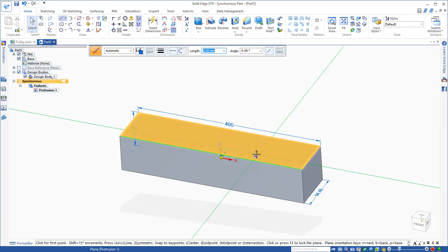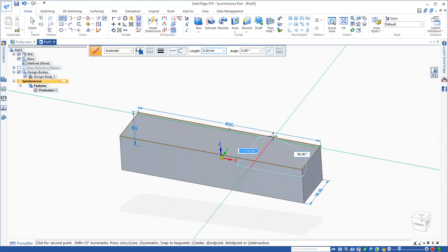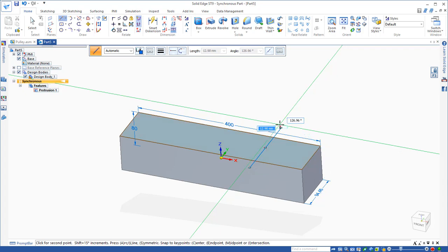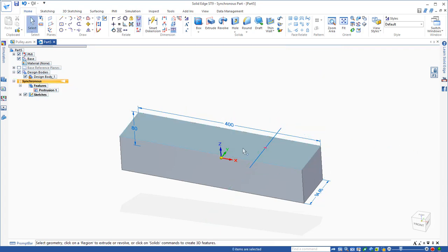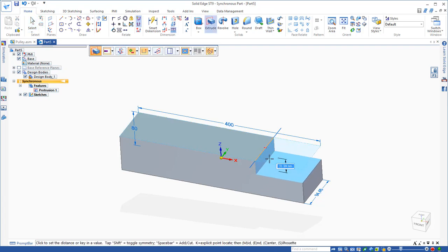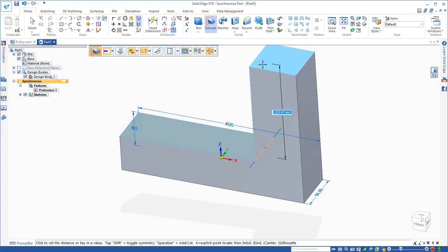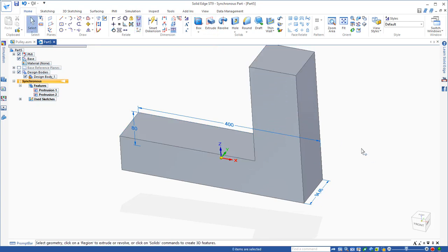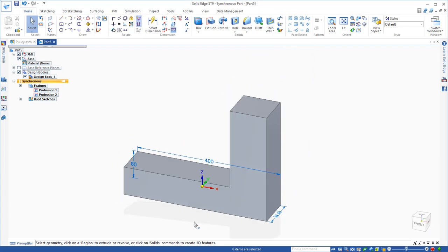I'm going to draw a line vertically across this face. Notice what that did. It broke this into more regions. I click on a region and start to drag. If I pull it down, it creates a cut. If I pull it up, it creates an extrude. Now, think about how I modeled this from the side view here. From the front view, XZ plane, I drew a profile and extruded it along Y. The next extrusion was straight up along the Z axis.